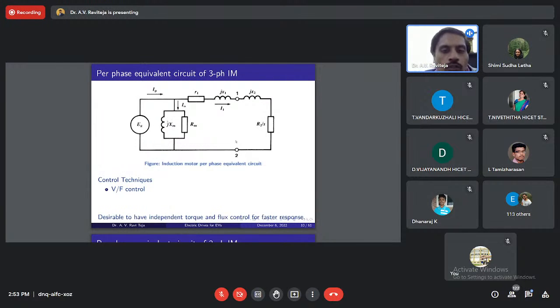So what I should be doing is, I should make sure that this inductor does not come into the change of I1 current. So for that, what we generally do is try to maintain I naught constant. As long as I naught is constant, this inductor is not disturbed, so its inductance will not come into the change of I1. So how do we do that?